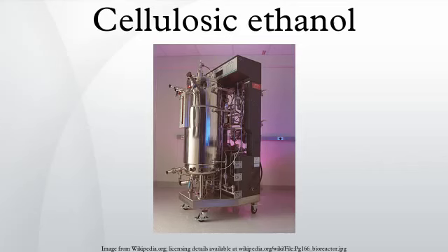This process soon found its way to the US, culminating in 2 commercial plants operating in the Southeast during WWI. These plants used what was called the American process, a one-stage dilute sulfuric acid hydrolysis. Though the yields were half that of the original German process, about 25 gallons of ethanol per ton versus 50, the throughput of the American process was much higher. A drop in lumber production forced the plants to close shortly after the end of WWI.